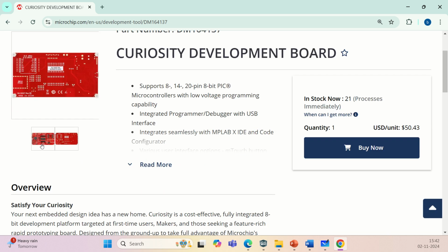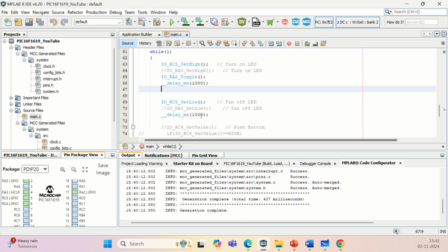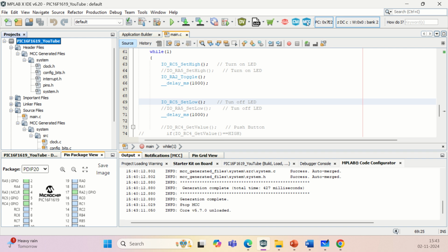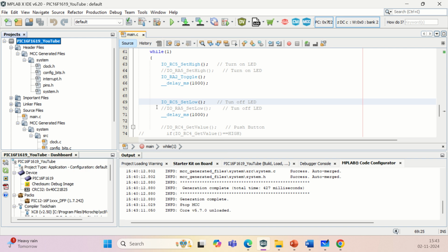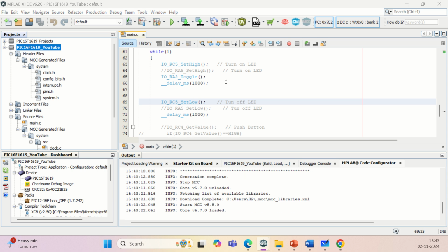All right. So our aim would be to find out how to get the ADC in this particular session. So this is RC0 port 1. So what we'll do is, let us open our program, and in this let us open MCC, and we'll configure my ADC point. Okay. So to configure that ADC point, make sure that ADC is connected to which line. Okay. So let us open this.